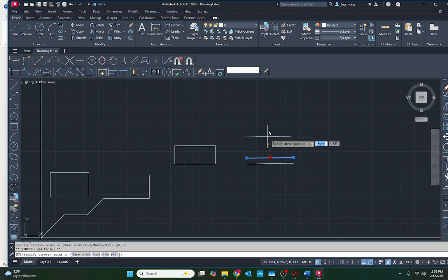With respect to move and copy, we can also do a stretch or a lengthen. In that case, instead of clicking on the center, we click on one of the ends. These little boxes are called grips. Generally you see them at the center and the end of every device, as well as often some of the other features. So if we click here, you'll see them on the center and end of every segment of this box, even though this box is only 1 unit.